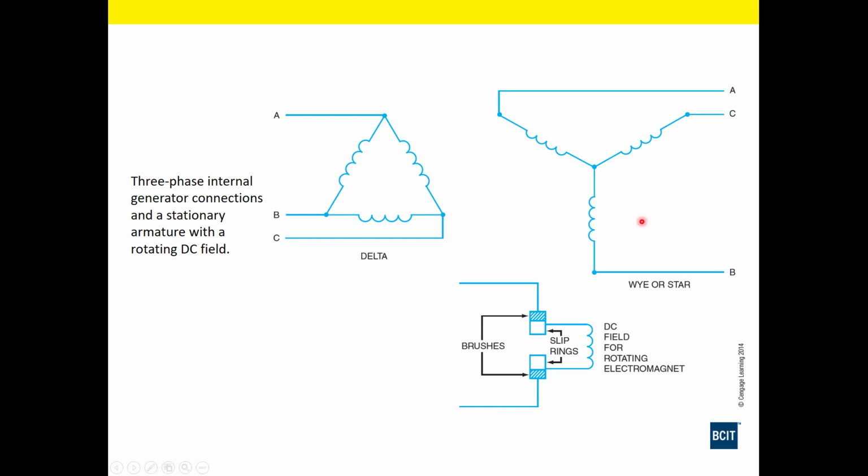Now, the connections for these alternators can be Y or delta connected, depending on the application and ratings. If we keep voltage rating for insulation in mind, let's say we have a generated voltage of 4,800 volts. The insulation rating for this winding, if it's Y connected, doesn't have to be rated for that higher voltage. It'll be √3 less. So if we have a 4,800 volt system, that's going to work out to 2,800 volts. So that's one advantage of connecting it as a Y.